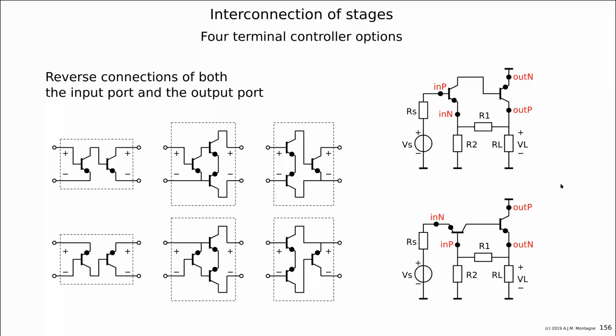Maybe it has consequences. It doesn't mean it behaves the same, because all bias circuitry here is omitted. And maybe the influence of bias on the noise and the distortion and parasitic capacitance is different at the different locations because you connect your bias sources to other impedance levels. So there can definitely be a difference between the two, but you can consider one or the other. And if you don't consider extra external components, no reason to distinguish one from another.